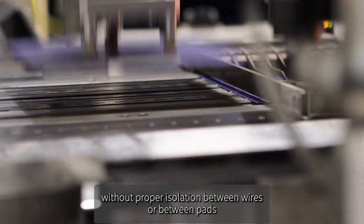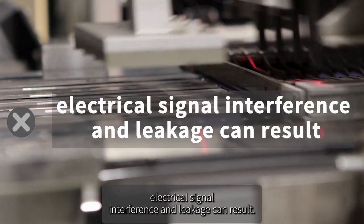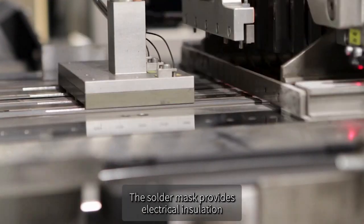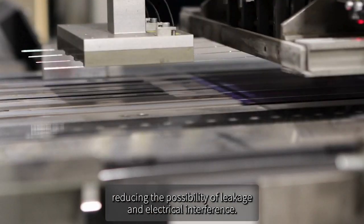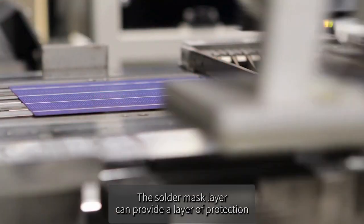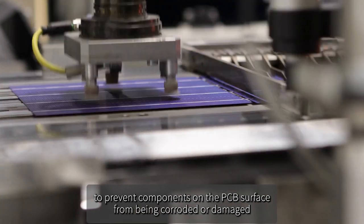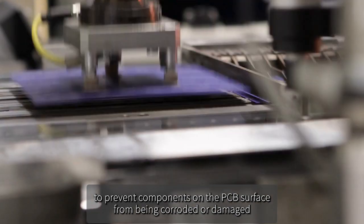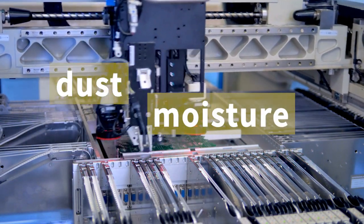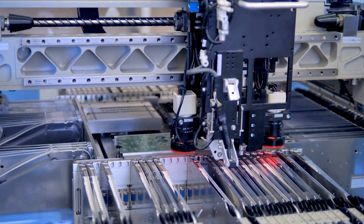On a circuit board, without proper isolation between wires or between pads, electrical signal interference and leakage can result. The solder mask provides electrical insulation, reducing the possibility of leakage and electrical interference. The solder mask layer can provide a layer of protection to prevent components on the PCB surface from being corroded or damaged by the external environment, such as dust, moisture, etc. This helps improve the reliability and longevity of the circuit.